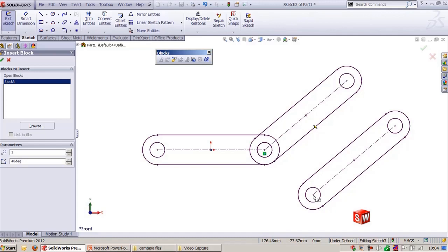Because in most companies, when they are trying to switch over from 2D to 3D, they will always have an issue importing the 2D drawings into their Sketcher environment. But here you have the advantage of browsing, and you can select the drawing file from an external file and insert it here to add features over the sketch. And that's all about creating a block and inserting a block.